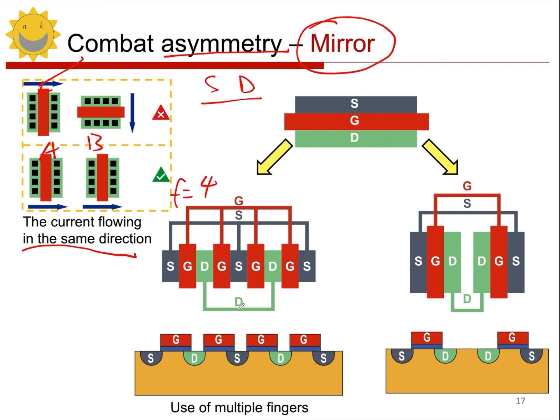Now let's take a look at the cross-section. It looks like this, right? The cross-section diagram is turned like this, and then, for example, our injection is in this direction, injected like this. So, if we do it this way, all the gates on the left side will have this shadow issue, right? They will all have the shadow problem. You can see that the overlap on the left side of the gate will be smaller, right? Now, regarding the drain of this gate, the overlap on the left side will also be smaller.